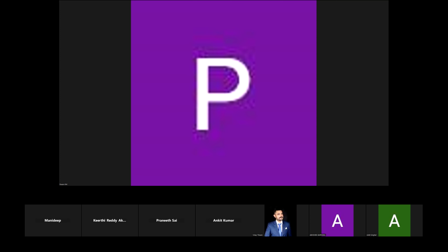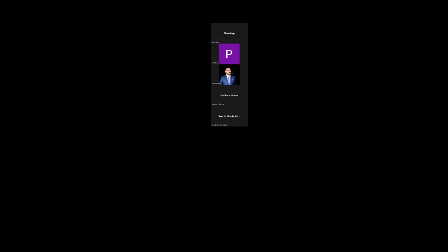APB is an on-chip protocol. We use it to establish communication between two peripherals, say when you have very low bandwidth of data. One side acts as a master, the other side acts as a slave. As many have told, it has three states: idle, setup, and access. Idle is the starting phase.